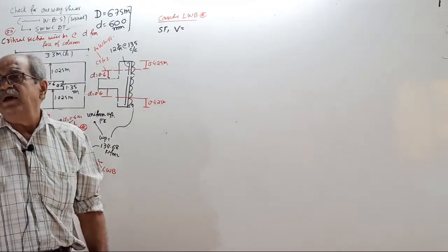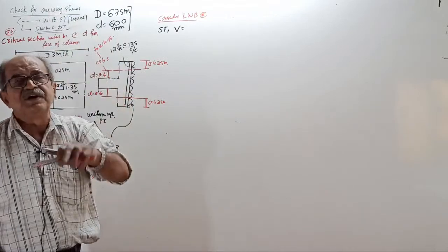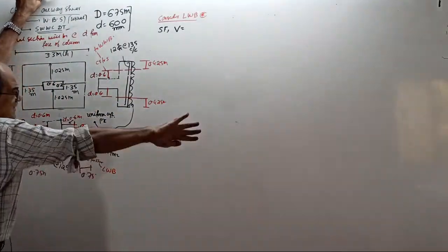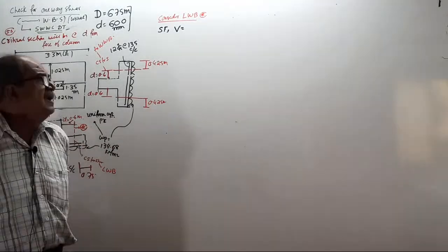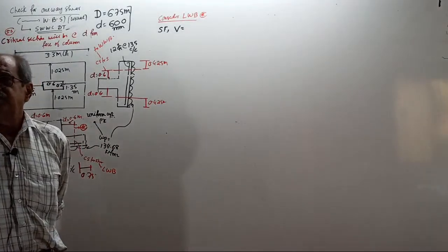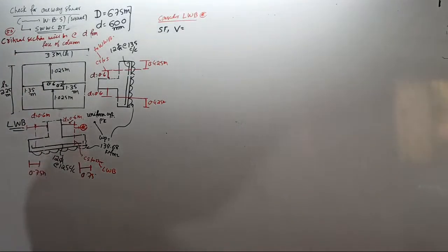For a cantilever in footing, when you want shear force, always look, tell me, right side or left side. I told very clearly. For shear force calculation, always consider from the critical section, left side or right side. For both BM and shear force, consider left side or right side first.